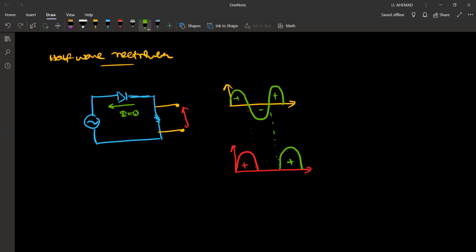From this complete wave, only half of the wave is being rectified. The other half is not used. So we call this half wave rectification. For this DC signal, we get a value that varies from 0 to a maximum value, and then there is no current for a certain period of time. Again, we get the next half cycle. To overcome this, we can use a large capacitor.